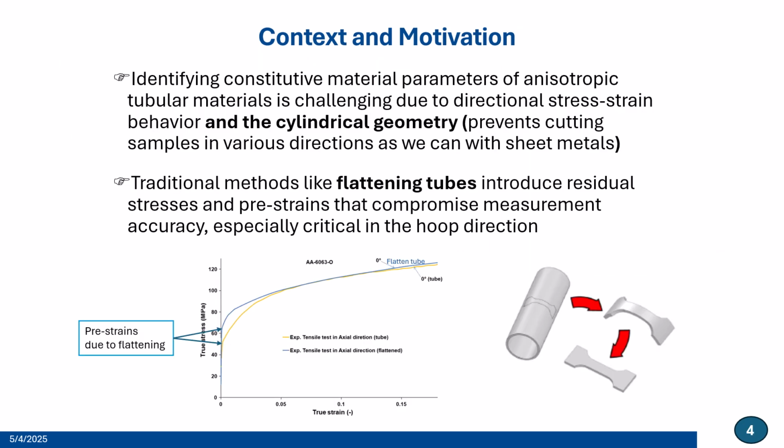So, identifying constitutive parameters of anisotropic tubular materials presents significant challenges due to complexities in the cylindrical geometry, which prevents cutting samples in various directions as we can do with sheet metals. Moreover, traditional methods such as flattening tubes for tensile testing introduce substantial residual stresses and pre-strains, as you can see